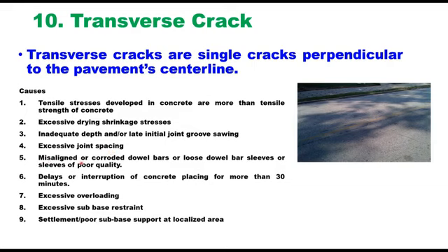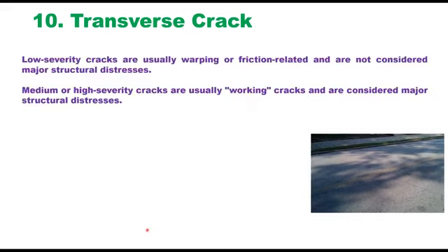misaligned or corroded dowel bars, delay or interruption of concrete placing for more than 30 minutes, excessive overloading, excessive sub-base restraint, settlement, or poor sub-base support at localized area. Low severity cracks are usually warping or friction related and are not considered major structural distresses. But medium or high severity cracks are usually working cracks and are considered major structural distresses.